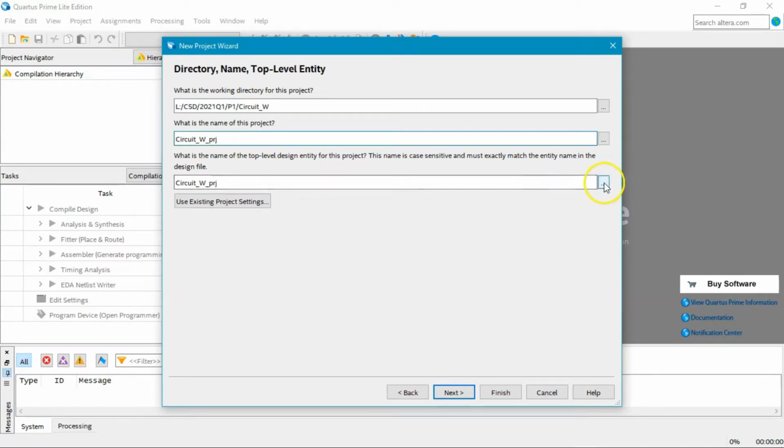And then you have to attach a new piece of information, which is the top entity. And the top entity in this case is simply scitw. So you will do that once and again. Okay, the project location, this is the name that we will attach to every single project. The coder underscore PRJ, keyboard encoder underscore PRJ, so this time it is scitw PRJ.